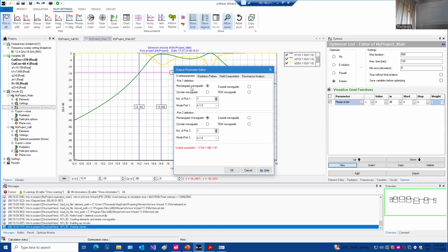It has to be the S11 parameter. For S11, you have to keep port number 1 as 1 and port number 2 also 1, because as Lakmal said, we are measuring S11, which means we are transmitting the signal from port 1 and measuring it again from port 1.